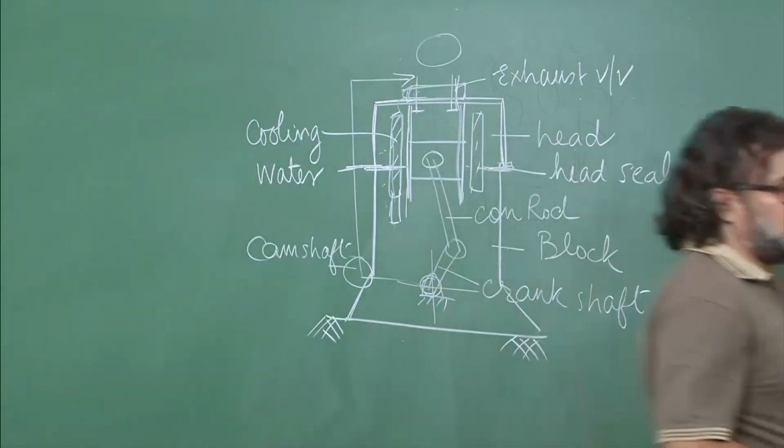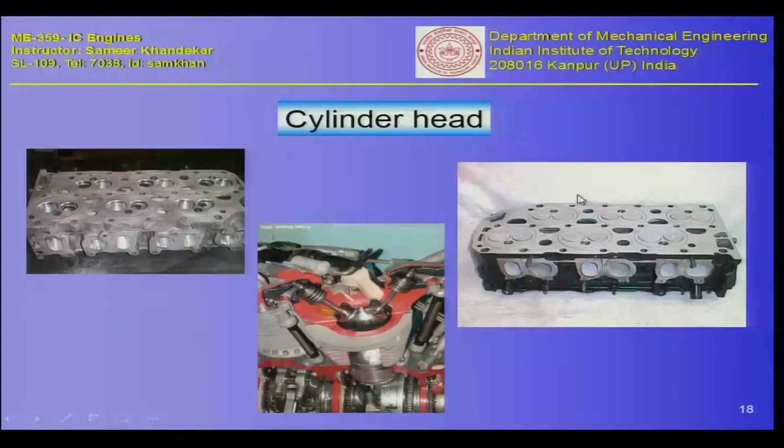So let us go back to our PPT, and you can see here, this is the block of the engine. You can see the valves, the push rod, the rocker arm, and then there is a retainer spring which will take this valve up after it is pushed down. So you have the inlet and the exhaust valves, and then the piston, the connecting rod, the timing gear, and the chain and sprocket mechanisms to operate these camshafts can also be seen. And the top portion is the head, and here is the head which has been removed and kept inverted.